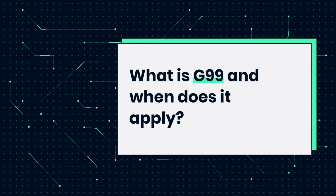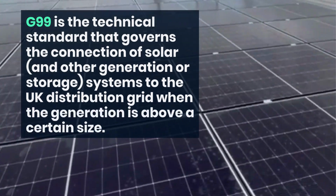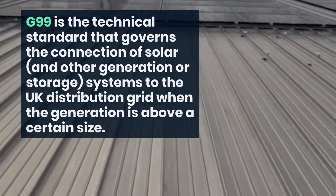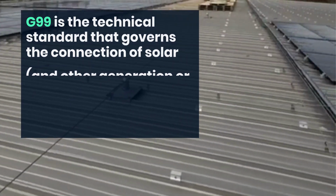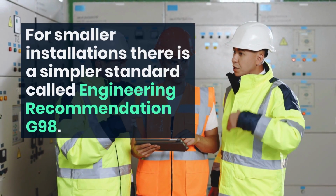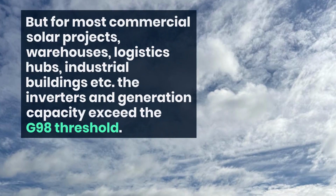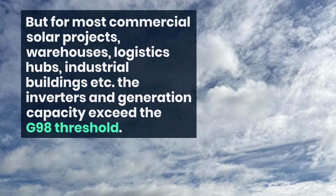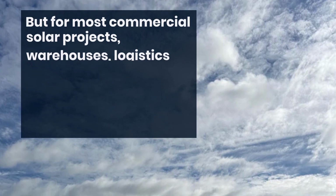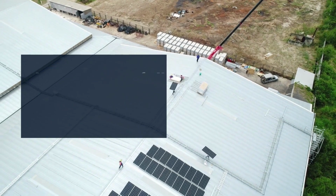What is G99 and when does it apply? Simply put, G99 is the technical standard that governs the connection of solar and other generation or storage systems to the UK distribution grid when the generation is above a certain size. For smaller installations, there is a simpler standard called Engineering Recommendation G98. But for most commercial solar projects, warehouses, logistics hubs, industrial buildings, etc., the inverters and generation capacity exceed the G98 threshold. That means a full G99 connection application is required.